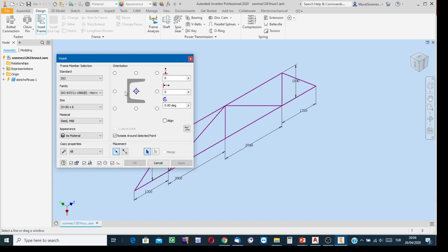Of course, selecting the cross section, we consider center of moment of the cross section, strength of the member, and some other design aspects. But here in this example, I selected this cross section, not I-shaped cross section, but C-shaped cross section. And then the third list is the list to select the size of the cross section, shape of the cross section, and then the size of the cross section. In this example, say I know 80 is the height of the cross section and 8 is the average thickness of the solid parts of the cross section.